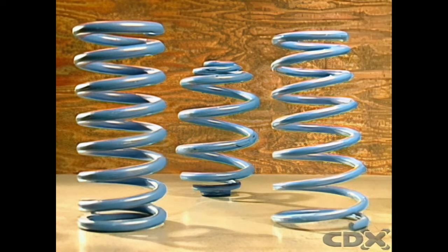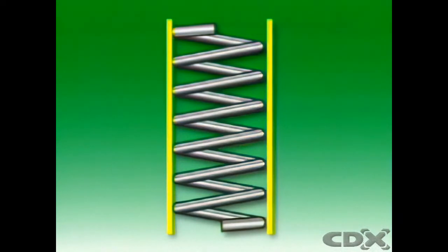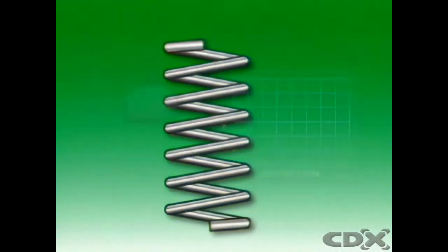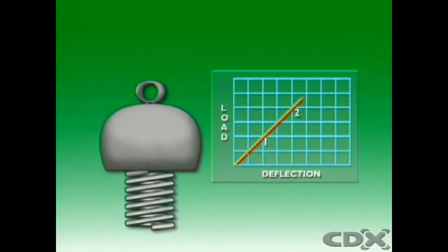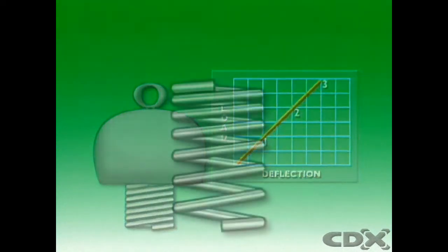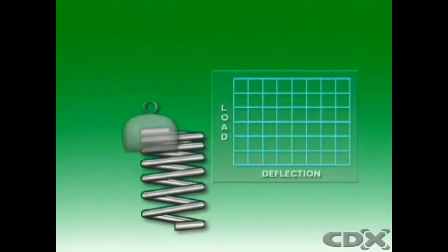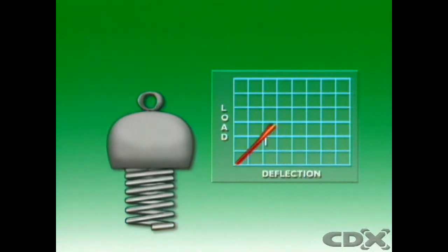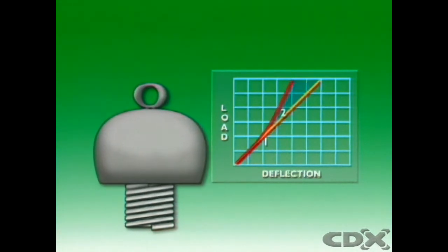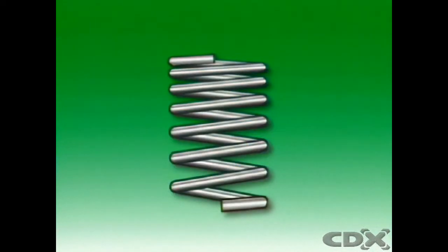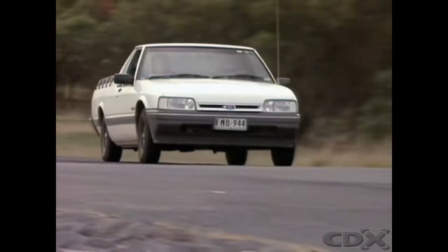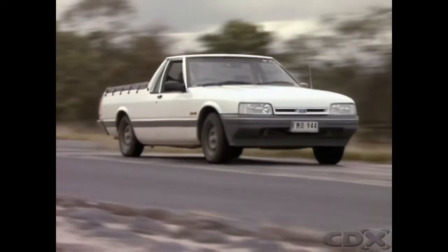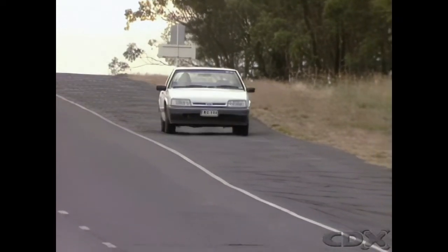Generally, a cylindrical spring with uniform diameter wire and uniform pitch has a constant deflection rate. Its length reduces in direct proportion to the load applied. When the pitch is varied, the deflection rate varies too. The spring is then said to have a progressive rate of deflection. Similarly for a varying wire diameter, and the shape. A spring with a progressive rate deflects readily under a light load, but increases its resistance as the load increases, which gives a softer ride.